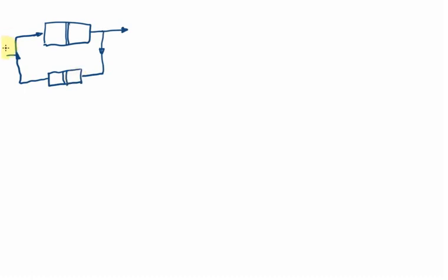So we can imagine injecting a pulse of tracer to the inlet here. And remember, we are only dealing with this inlet and this output, because in principle we have some real reactor somewhere, and there's some kind of complex mixing pattern going on in here, and it might be that this system that's been proposed is a model for the kind of mixing going on in here. And so in this real reactor, we can only take samples or make injections here and here. So we are injecting some tracer here, and we are taking a measure out here.